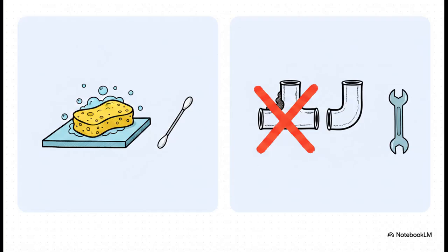Now, how does our mindset change this scenario? The reactive approach would be to just clean harder, right? Take some standard swabs from the flat surfaces and basically hope for the best. But using a proactive FMEA, the cross-functional team discovered a major hidden failure mode. Invisible dead legs in the piping where residue could easily build up. Because standard swabbing couldn't even reach there, they assigned a terrifying detection score of 10, meaning it was virtually impossible